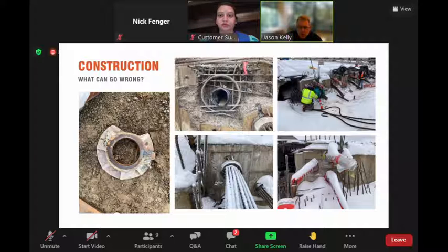You know, is the steel in good shape? Is the concrete in good shape? Is it holey? Is the timber rotten? So we look at the condition. That's the one thing we look to see if it's replaced or not. And if it gets in bad enough condition, if it's in poor condition or serious condition or things are starting to fail, then we'll replace it.